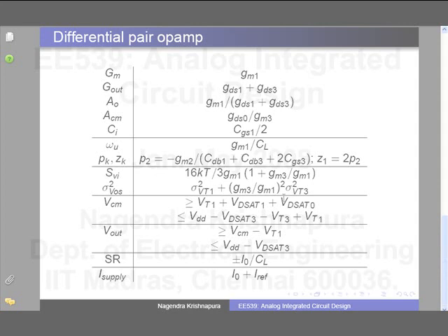First of all, now you are messing around with too many other things. If you increase GM1, your unity gain frequency will increase. That may or may not be desirable. Okay. So you will try to reduce GM3, or what else can you do if you don't want to do either of these things? You want to keep swing limits the same, everything else the same. What are you going to do?